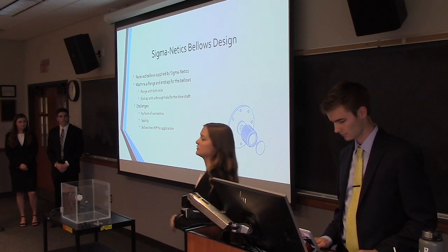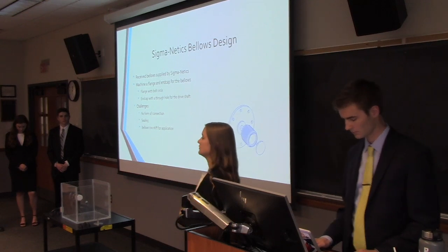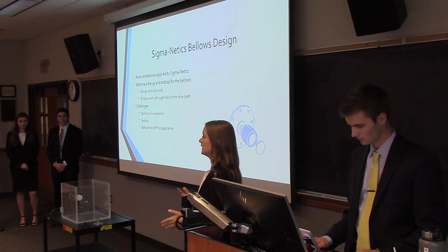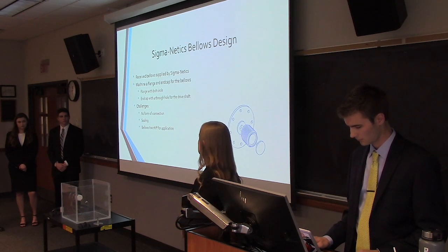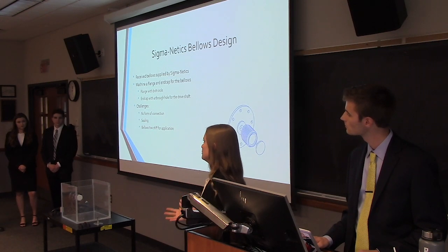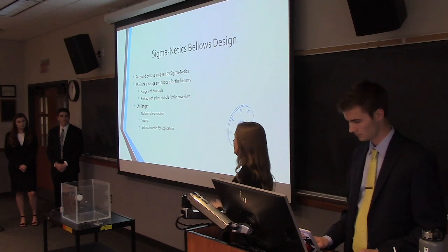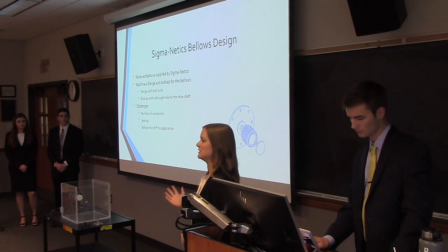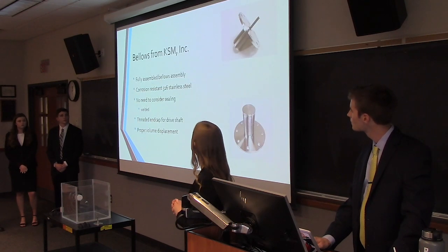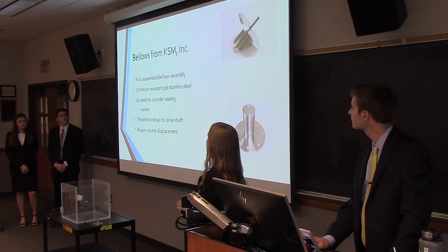Since the bellows are made out of a material known as Monel, our Grove City machine shop does not have the capabilities of welding Monel, so they would not be sealed properly. With the sealing, the water would leak through and would affect the way the turbulence was generated and how the bellows behaved. And ultimately, the bellows were just too stiff for our application. They didn't fall well in line with the design parameters that we were looking for. So this led us to choose the design that we have now.